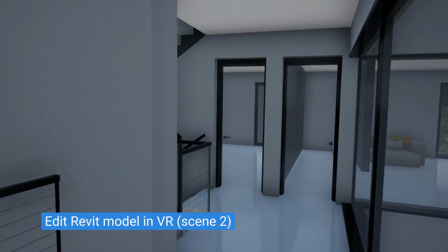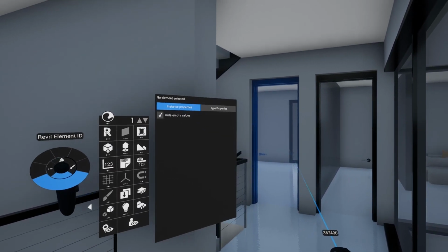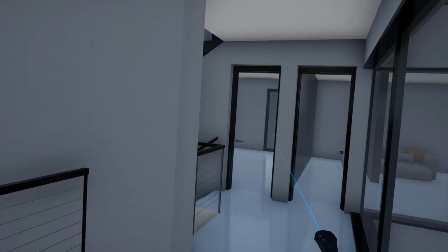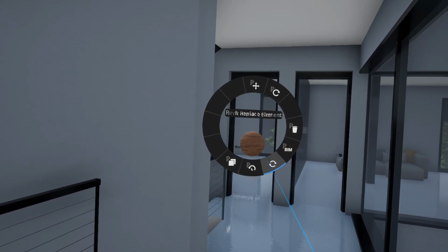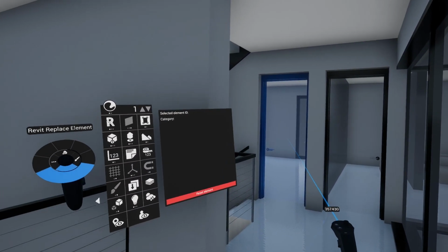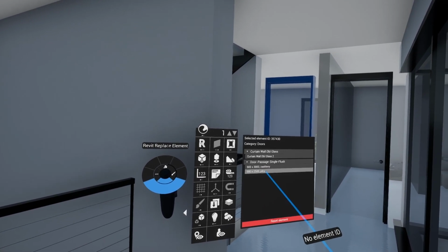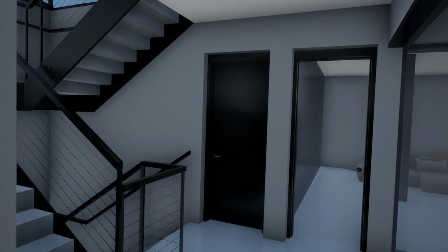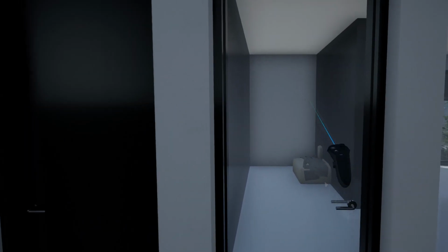So let's go to another part, and this part is the hallway. Again, there is some door, we can display parameters. I know it's glass, so I want it full. So let's use another function, and it's replace. Let's replace this family with another family. Let's click on it. I have two options. One option is glassy, one is full. So let's select full. I want this full, right? And there would be a nice window over there, right?